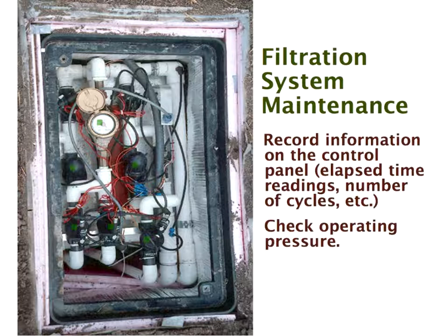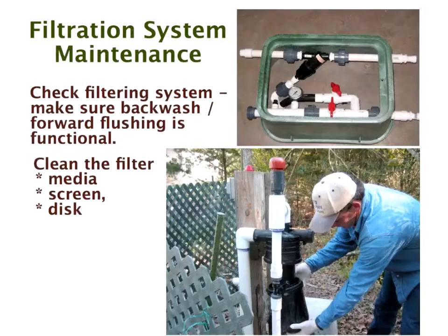Okay, then a part of your maintenance is to record the information on the control panel and write it down, and check your operating pressures, and of course check your flows, which I presume is going to come up at the next slide. Okay, check the filtering system.